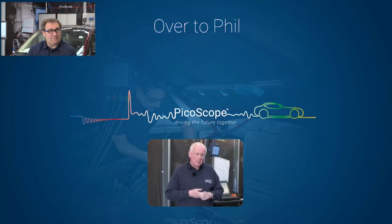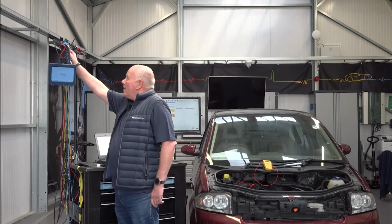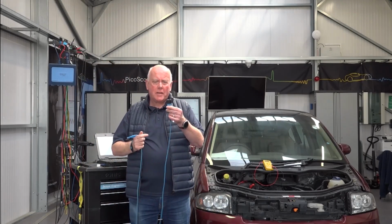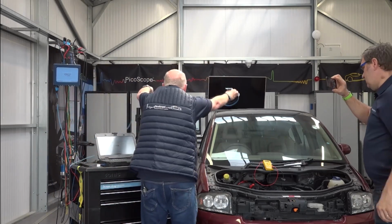Okay, I think that's probably enough of me for a short while. So we're going to pass you over to Phil now, and he's going to take you through multimeter versus PicoScope on a camshaft sensor. Over to you, Phil. Thanks, John. Hi guys, right, so what we're going to do now is we're going to connect onto the component. So I'm going to take my red test lead, BNC plus. So of course we're now going to put that onto our scope on channel A. And then I'm going to feed my wire around.